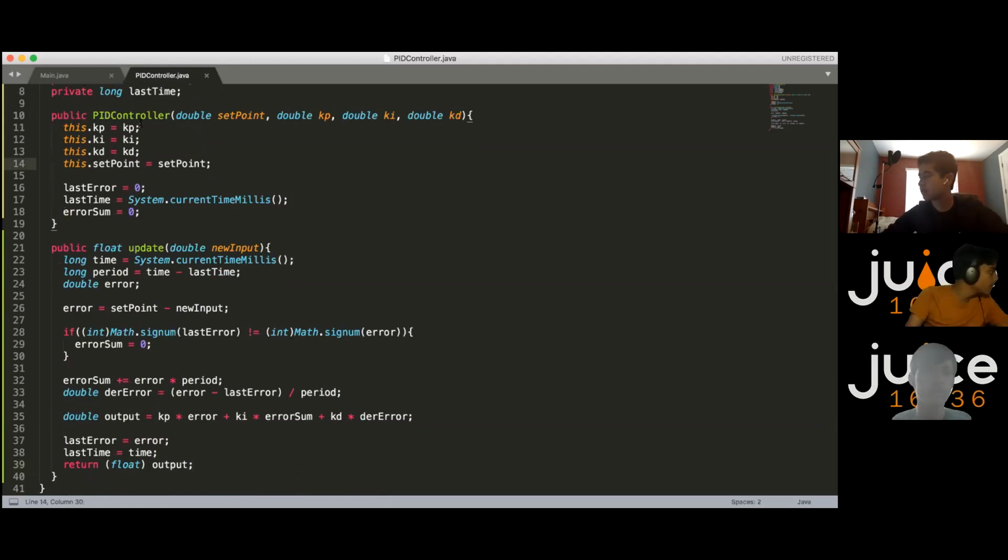We had a question on, is it possible for the integral value to be larger than the proportional value? I'm assuming you mean the constants for the integral and proportional. Normally we'll go over what some possible constants are, but normally the proportional constant is far higher than the integral constant. If you think about it this way, the integral is the entire area underneath the error versus time curve, whereas the proportional value is just the error at that time. Meaning you want to make your KP normally higher than your KI.